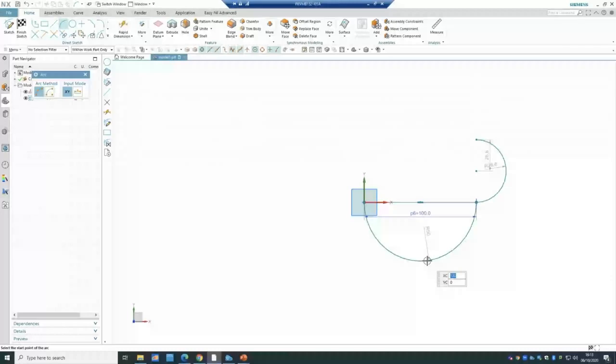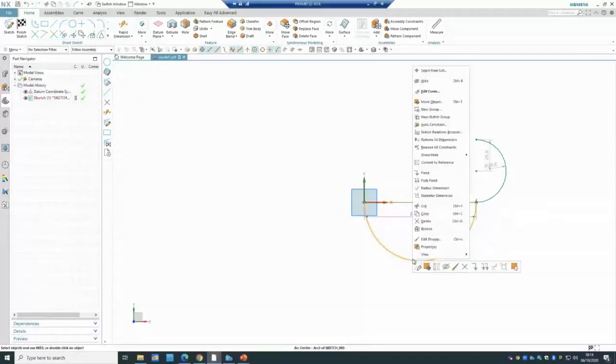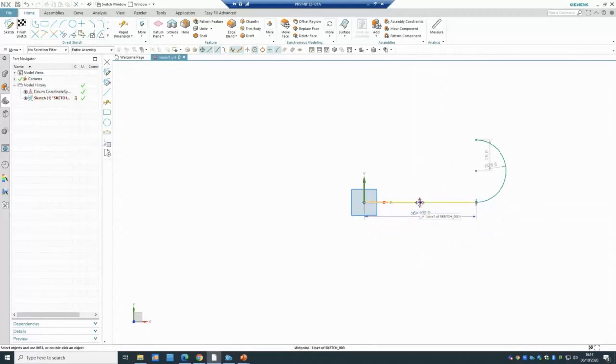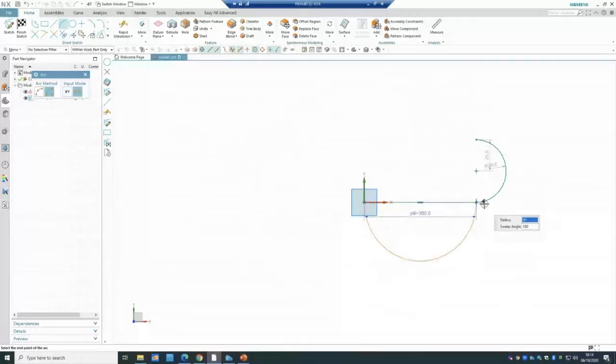There's a different way of making an arc, and that's the one with the center. What you do is, the first point is the starting point, the second point is the center of it. If you have a look, you will see that technically the center is driving everything. So we'll do it again with this one. The first is where you want to have the center. For instance, let me delete this one, and let's say I want to have this one as a center. So I will go with the arc. We'll choose the point in the middle and the second point. And now I would be able to draw a half circle or even something like that.